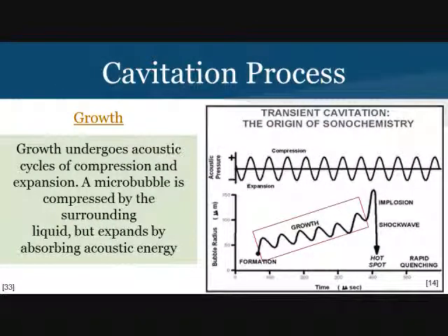Cavitational bubbles undergo acoustic cycles, namely those of compression and expansion. Acoustic cycles are influenced by acoustic energy absorption, which is, in turn, influenced by the surface area of the microbubble. The greater the surface area, the more acoustic energy absorbed, the greater the vapor pressure from within the bubble, and the faster the expansion against the liquid solution.